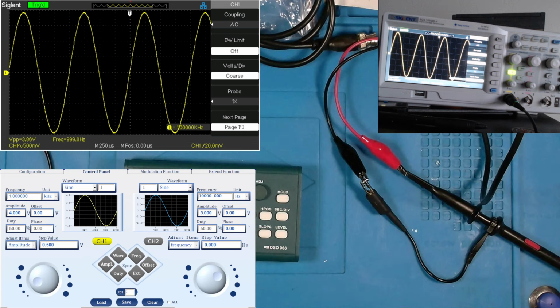This is a 50 megahertz oscilloscope, so I could get up beyond audible range into the RF range, low RF, and I would need to see those frequencies, in which I could do. Now, could I go to a frequency above 50 megahertz? No, not with this oscilloscope, because its bandwidth is 50 megahertz, unless through a non-linear device I heterodyne 2 frequencies.